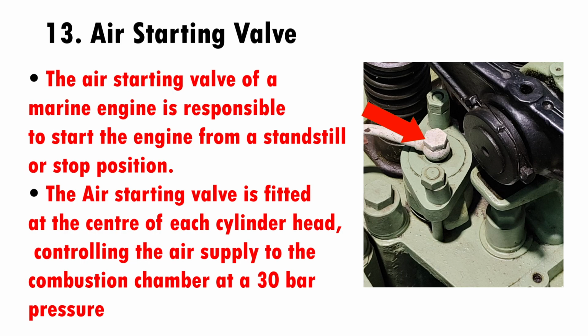Air starting valve. The air starting valve of a marine engine is responsible to start the engine from a standstill or stop position. The air starting valve is fitted at the center of each cylinder head, controlling the air supply to the combustion chamber at a 30 bars pressure.